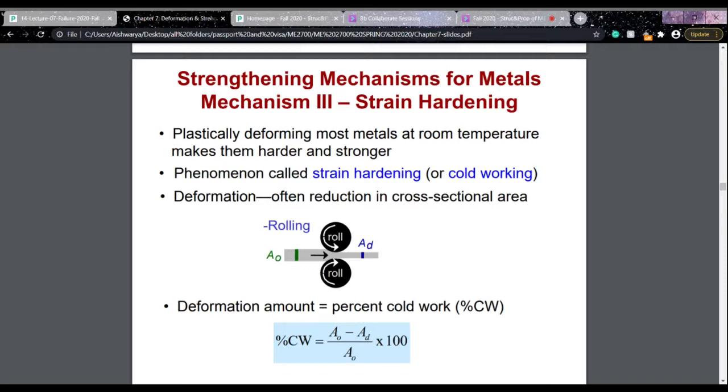During the plastic deformation, dislocation density increases. The distance between adjacent dislocations decreases because of the strain field interactions, and the motion of dislocations is arrested or restricted. So the material becomes harder and stronger.